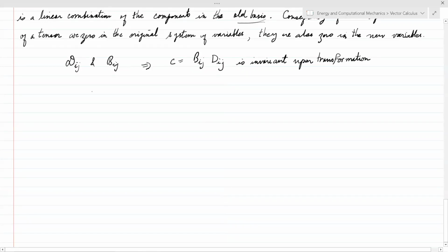I already know how to transform things, and we learned how to do that earlier. So let's look at how to do Dij prime. I'll write the A's first, and then the D. My next step is to write I here and J here, and then here I'll pick two variables that are not used. So Ij is here and then the K and L summation here. This transforms a second order tensor from one coordinate system to another using the direction cosines you learned about already.